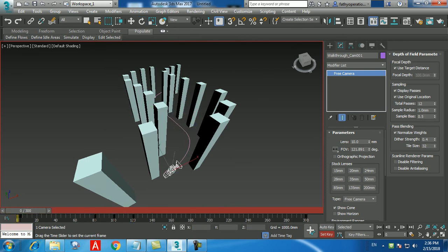So every time you change the camera angle, is it controlled by data? You can use the Z-axis, right? Z is this, like this. This is going to be the x-axis. But whenever you move it, don't forget to click on the key to record it. This set key. So when you move from one timeline to another timeline, you have to click the set key.